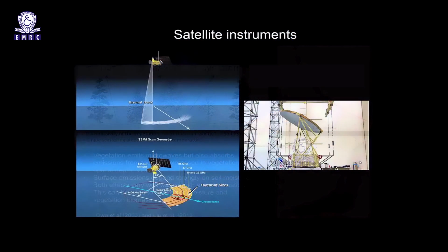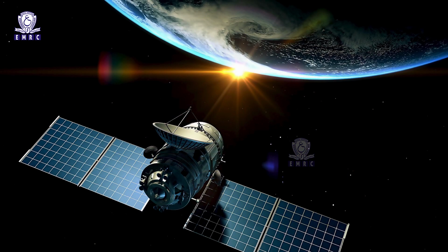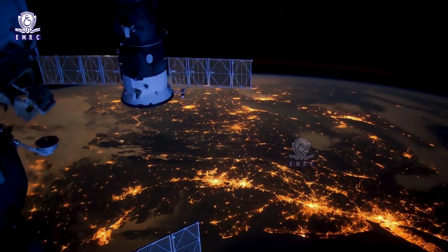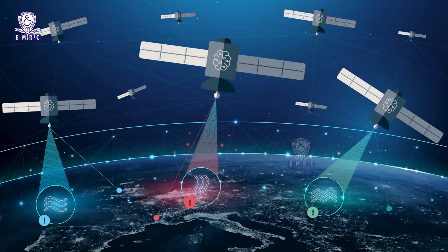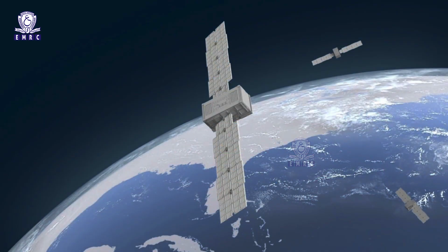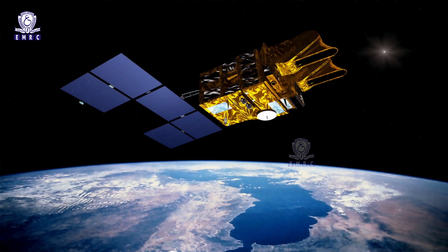The radar is an active microwave remote sensing system which illuminates the terrain with electromagnetic energy, detects the scattered energy returning from the terrain and then records it as an image. Intensity of the radar return, for both aircraft or satellite based systems, depends upon the radar system properties and terrain properties.